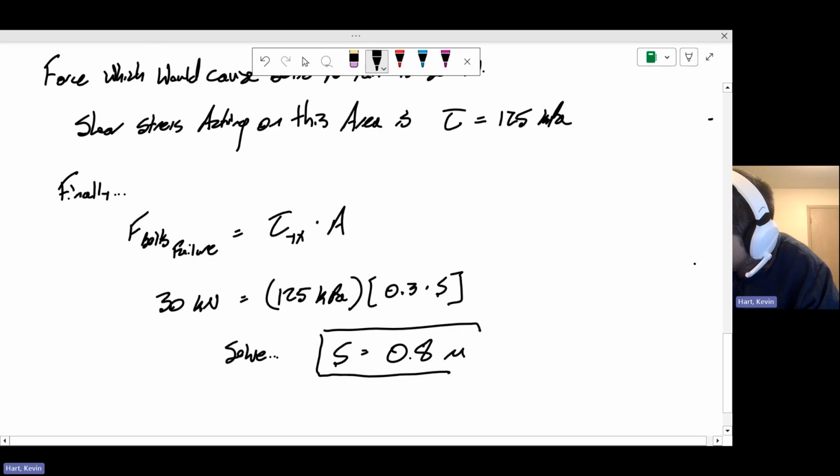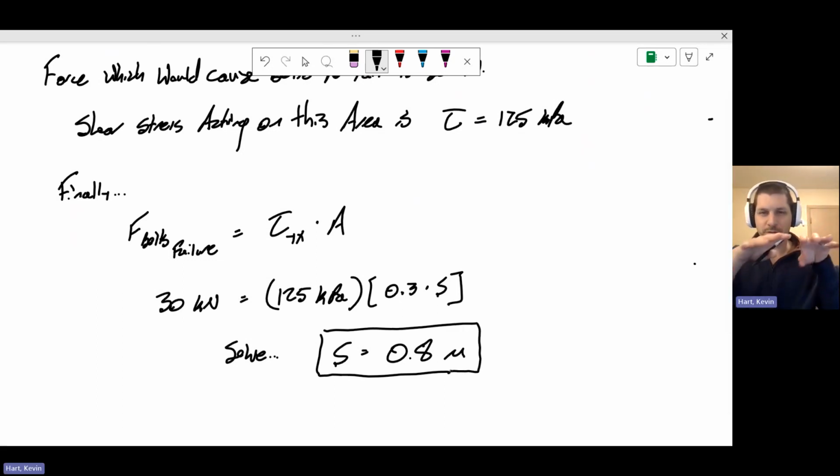Bit of an odd problem. It's transforming some shear stress that we have into this longitudinal shear stress that exists between the boards, and then using that to inform the spacing of our bolts required to keep this thing alive.